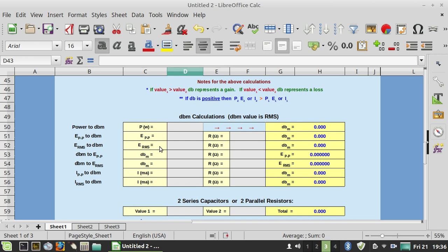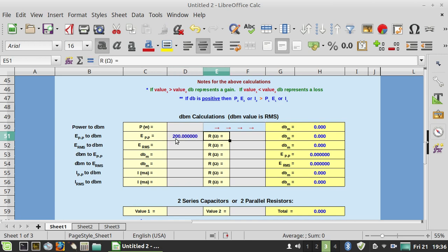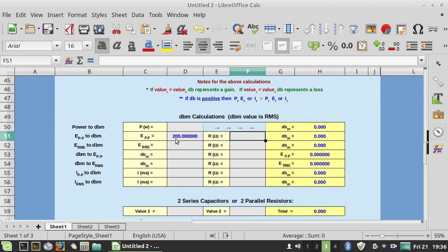So I needed minus 25 dBm or better. I've heard that 200 millivolts would achieve that. 200 millivolts, the input impedance of the mixer chip is 1500 ohms.